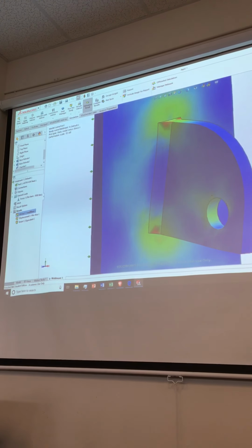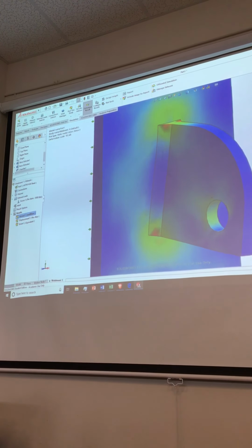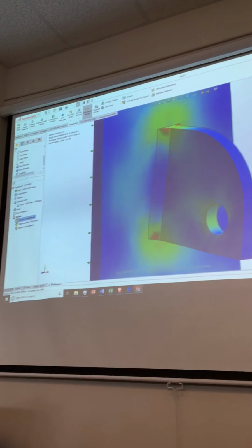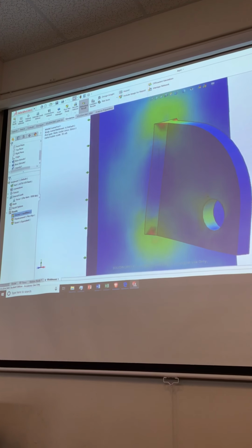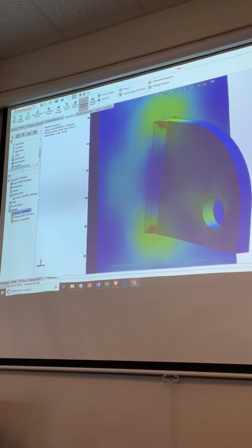Your car from it, okay? And what's that going to do? Well, it's not going to get any tensile stresses in there, right? Can't get tensile stresses in that hole because that would require that I'd be yanking hold of the material and pulling on it, right? I'd have to weld something in there, some kind of crazy thing to try to get that, right? So my loading around the holes is sort of by definition right now, bad, right?